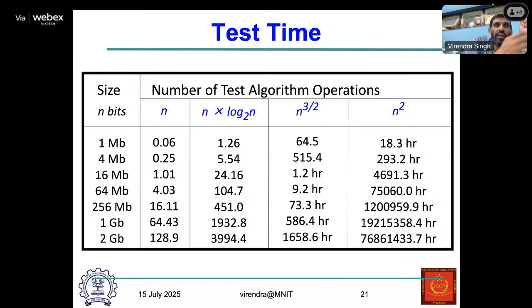Now with every memory element, if I can check all these operations, then I can conclude that the particular element is good, right? When I store 0, it is storing 0. How do I get to know whether it keeps storing 0? First I write 0, and after some time I check whether it returns 0 or not. If it returns 0, then that element is good. If I write 1, and after a while I check whether it returns 1 or not. If it returns 1, then I can say it has retentivity of 1.